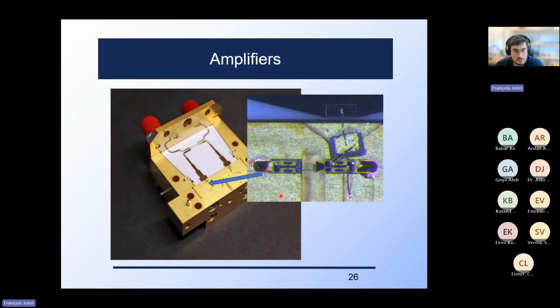And so, going very fast, we have seen local oscillator, mixers, and the front end. And now I want to show you how we extract the intermediate frequency. For that, we use PCBs, superconducting PCBs that allow us to have extremely low losses in the transmission of the signal, because so far we haven't got any amplification yet. So we just have the mixing, and we extract the mixing with a wire bond to the superconducting PCB.